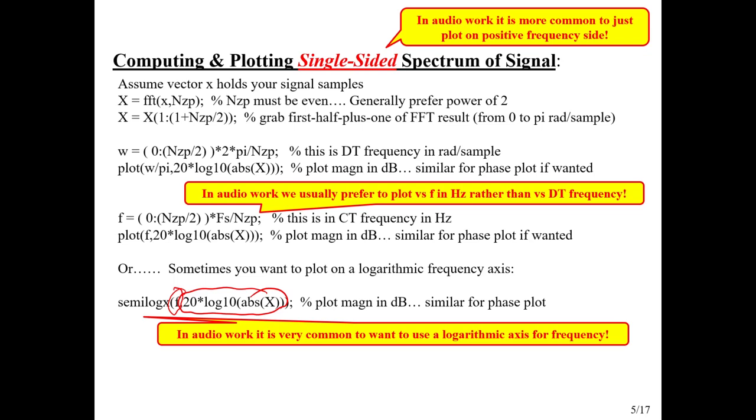So we're really doing log magnitude versus log frequency. It's just that we're seeing the log frequency explicitly, and we're seeing the log magnitude in terms of dB. And we could do a similar phase plot, although obviously not in log 10 of the phase. Now, when you run that command, since there's going to be a 0 in this f vector, there will be a little warning. MATLAB will tell you, oh, I can't plot log of 0 on a semi-log axis.